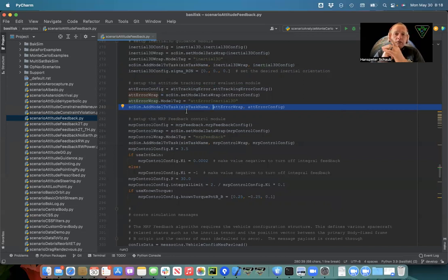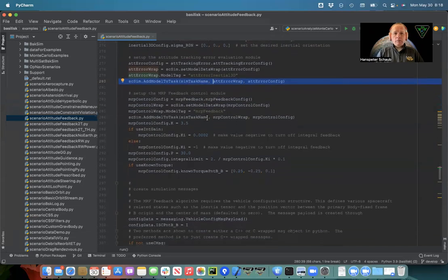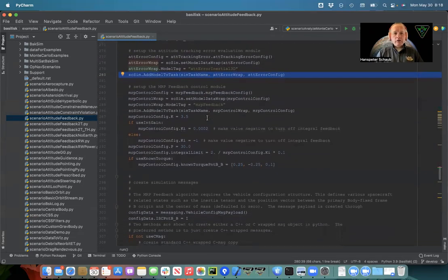If you needed the reference frame to be matched not with the body frame, but maybe with some cousin of the body frame, you know, instead of having a one axis look forward to the spacecraft, it looks to the right because that's where the docking port is or something, you can put in a correction and it will drive your reference to the corrected body-fixed frame. We're not doing that here. So we're just configuring it, and then by default, it computes the error between B and R. That's all it does. But it does it in a very general way, which is actually nice.